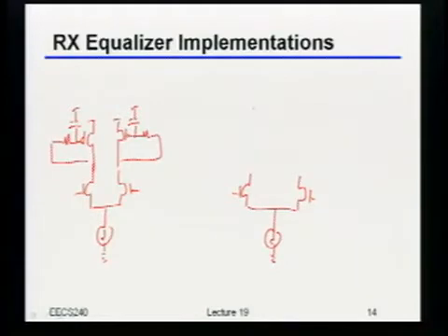Okay? So this is going to look a little bit funny at first, but we'll see how this works in 1 second. So imagine that somehow, I'll draw it this way. Imagine I just took for my load, and rather than putting PMOS transistors, I put NMOS source followers. Okay? Seems a little bit odd, right? But okay, we'll see how we'll fix this in 1 second. Okay, so at DC, what would be the impedance I see looking up into there? 1 over GM.